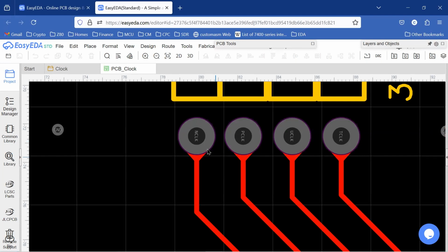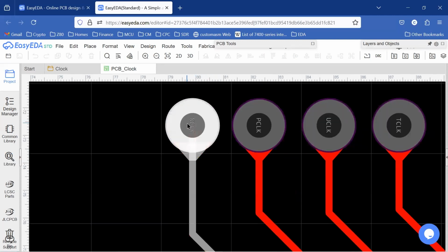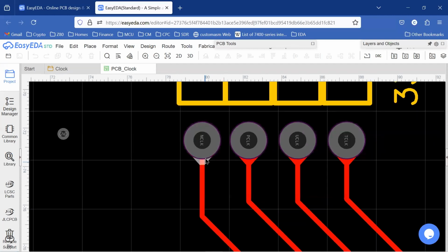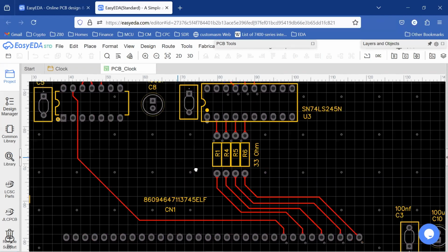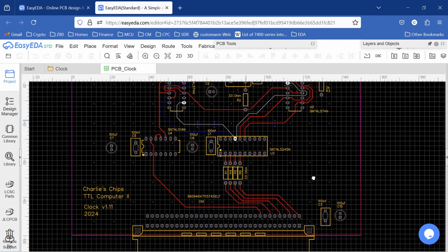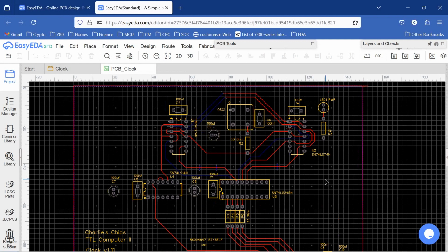And it also allows for tolerance if the drill in the fabrication process is not exactly on center, since we're increasing the surface area of the pad, so that we still get a good pad and good adherence with the trace. Okay, so I think that's everything that I did on version 2.